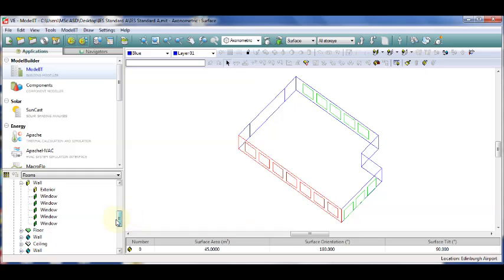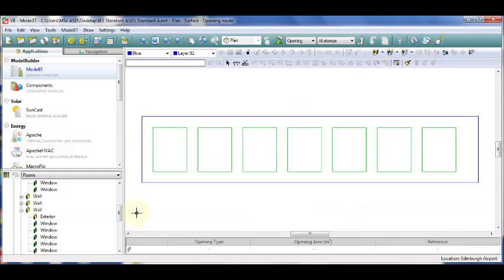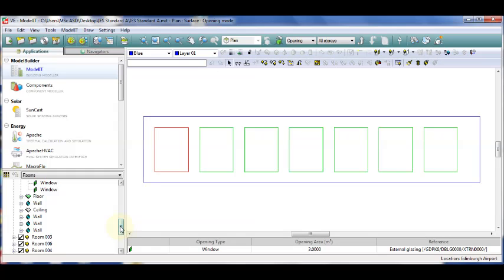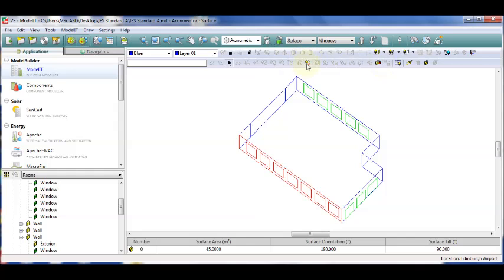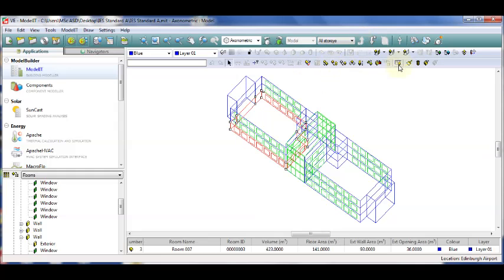At room level, you can pick on a particular component that you want to see. And actually, if you look over on the left here, it will have highlighted a particular wall, which has now become open. If I go down a level, it'll tell you which window I am concentrating on here. There, that one there. And it says what it's made of and how big it is. As you go back up the levels, you'll see the different tools become available. Like that one's become available now, and now all of these become available. So certain things only work at certain levels.